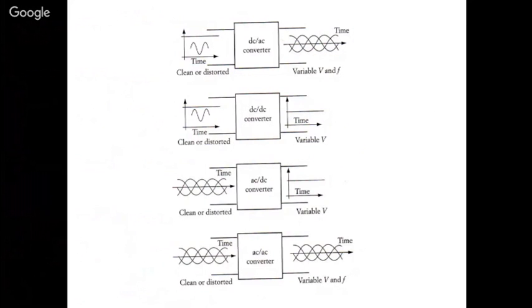Okay, so that is in case of boost. Anyway, I have not drawn the circuit here, but initially the switch will be in the middle, parallel to the source and the load, and there will be an inductor in series with the source. So when you turn on the switch, the inductor will get charged, and when that inductor is fully charged, the inductor voltage is equal to the source voltage. Now the switch can be put on the other end, so this whole voltage, that is a double voltage, will come across the load.